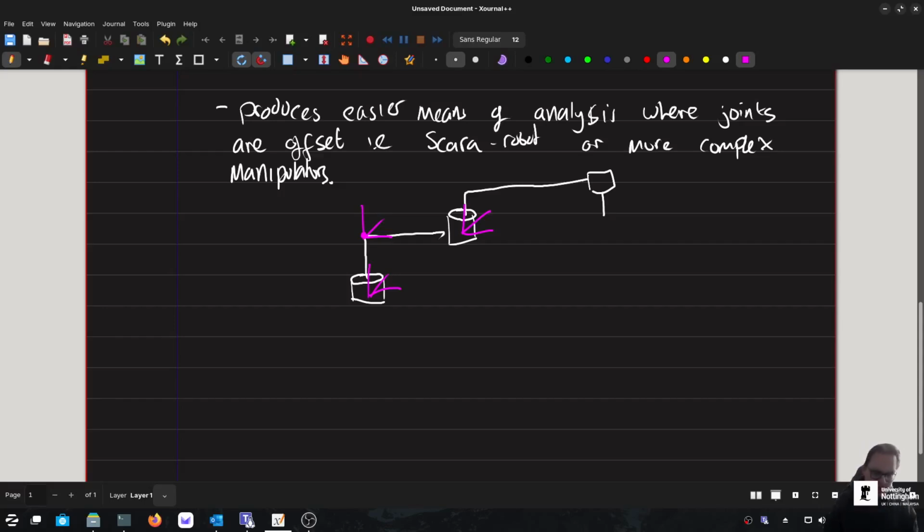With the DH algorithm, this right angle turn is already preset into the algorithm, as you might be aware from the lecture already. So that's why it makes it a bit easier. We don't have to make multiple frames. The DH algorithm allows us to just go from one frame to the next frame and accounts for any offsets already made in the robot. So I'll leave that there.